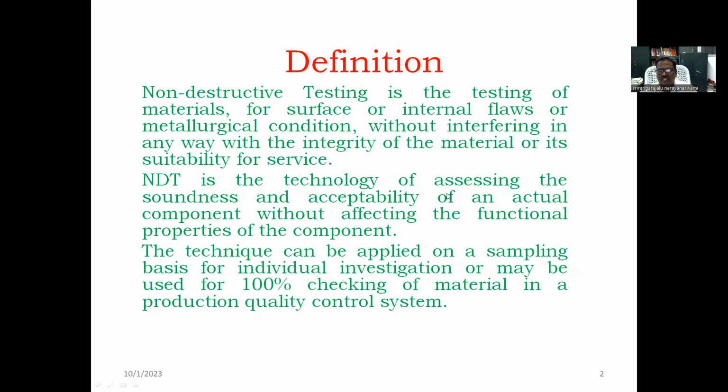NDT is the technology of assessing the soundness and acceptability of an actual component without affecting the functional properties of the component. The technique can be applied on a sampling basis for individual investigation or may be used for 100% checking of material in a production quality control system.